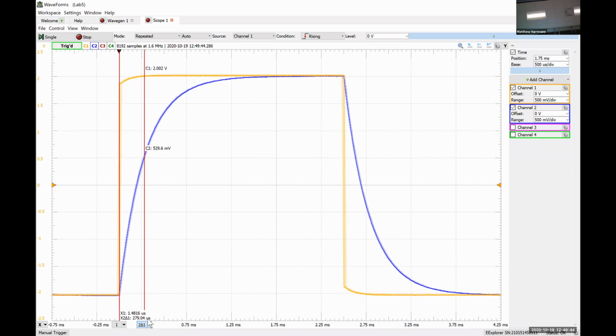All right, so most of the lab is done. There's just one last little thing that is kind of a discussion type question. But yeah, this is the voltage drop over a capacitor. We are seeing that the inclusion of a capacitor into this system forces the response to have that exponential growth because the capacitor voltage cannot change abruptly. So we are seeing literally what the math described perfectly based on our simple derivation that we did in class about how the voltage drop and current over a capacitor are related.